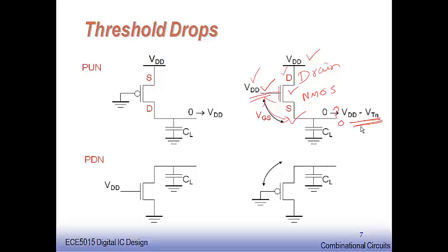For example, if I am working with a 1 volt power supply with a threshold of 0.4 volts, the moment I get 0.6 here with 1 here, the difference would be 0.4 volt. It is enough to get this device on. But the moment I expect the output to go beyond 0.6, this 0.4 volts would have to be less than 0.3 or 0.35, at which point the device is not supposed to be conducting. So a stage will never come wherein the output voltage reaches VDD.